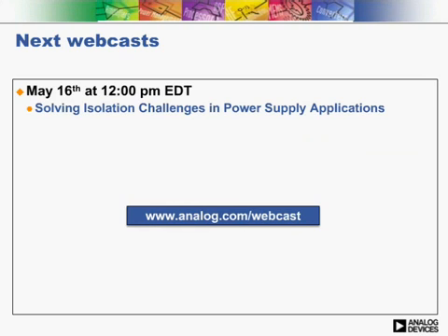And then in DAC applications, a number of these require that all the DACs in two or more chips have the same data in the DAC output latency within one DAC sampling clock cycle. And if the same signal is input to all DACs, the same signal needs to be output by each DAC on the same FDAC clock cycle. Such applications would again be communications applications like wireless macro base stations, again military radar, and then I&I waveform generators.